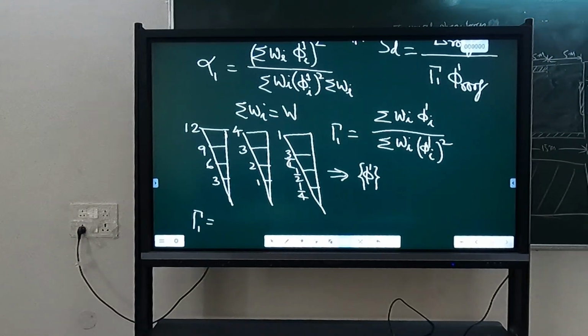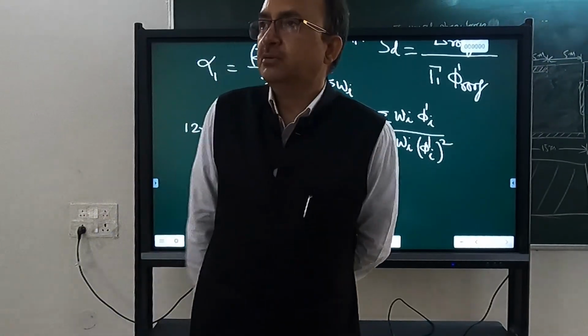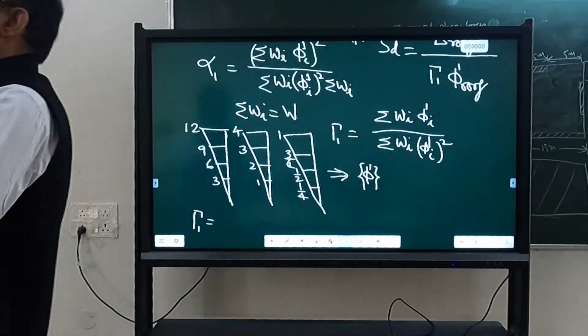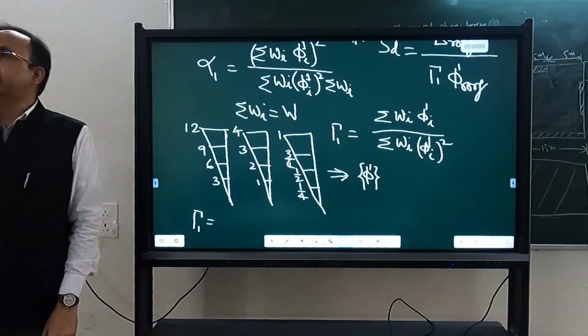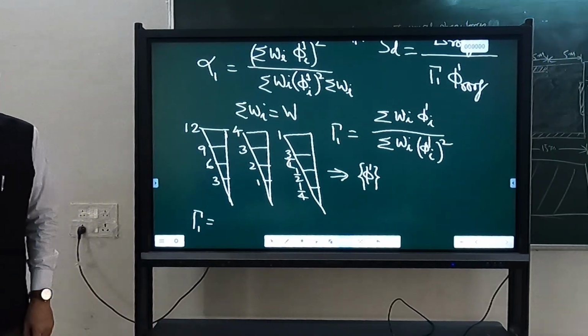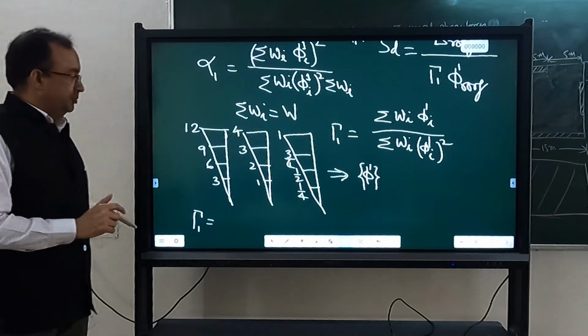Due to that, the actual strength will be higher than what you calculate from AH into W. And there is a nonlinear relationship between base shear and displacement. That's what we have done in more than half of this course. So VB is not AH into W. It is variable. VBD is AH into W. But thank you for asking these questions.